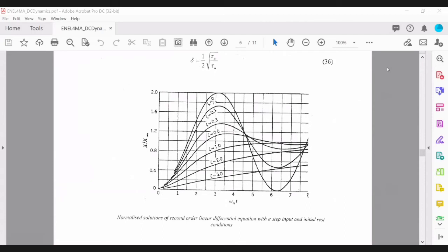As you can see, when your damping ratio changes, for example if it's higher than 1, you get what we call a first order response following a step input. Whereas if your damping ratio is below 1, you now get that overshoot. Your system turns into a second order system where you have oscillations in the response.